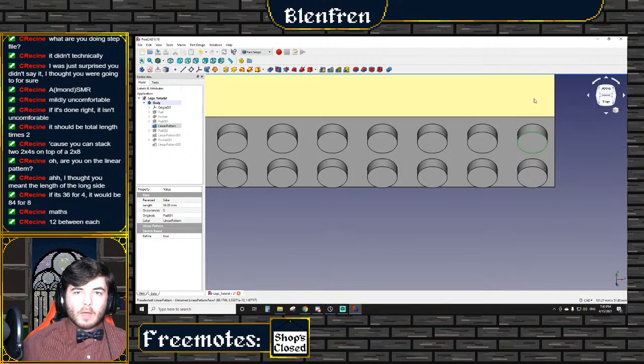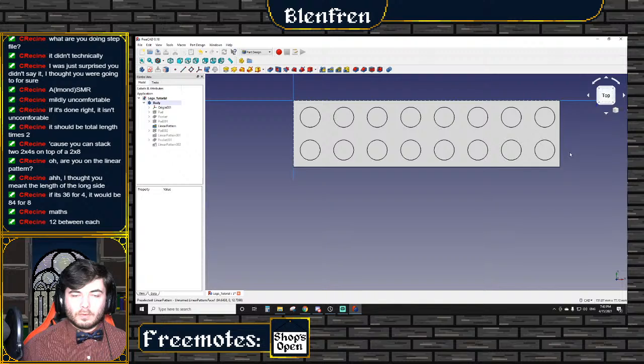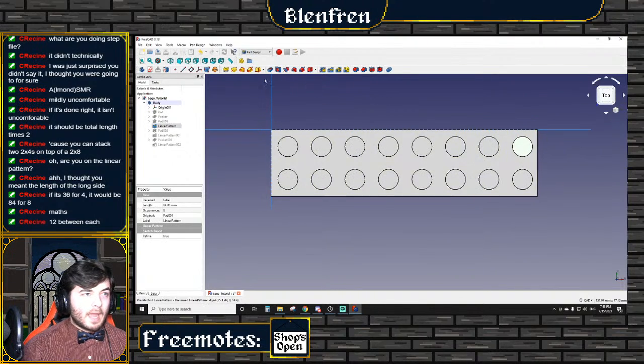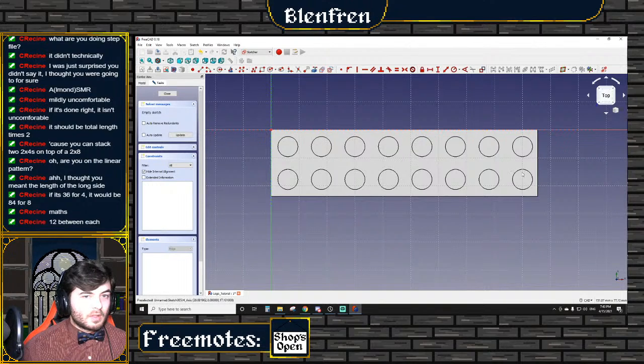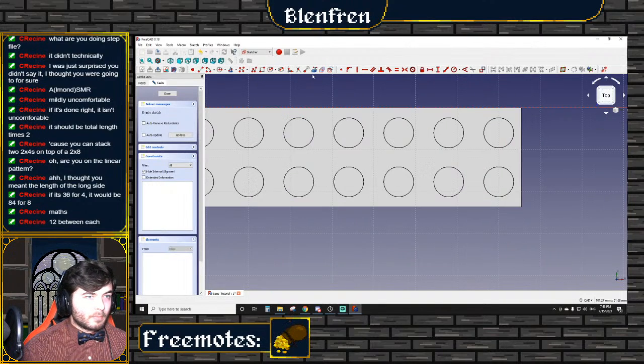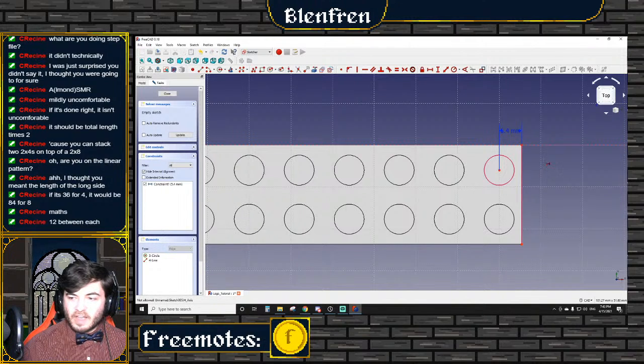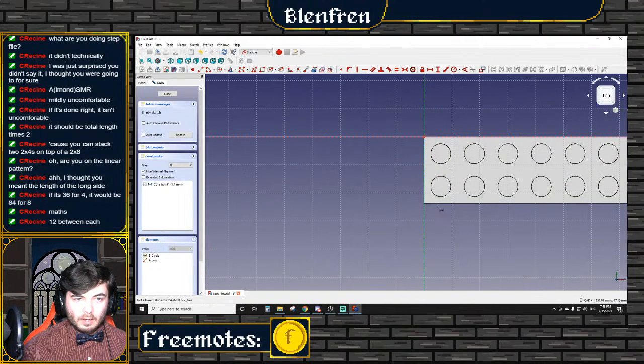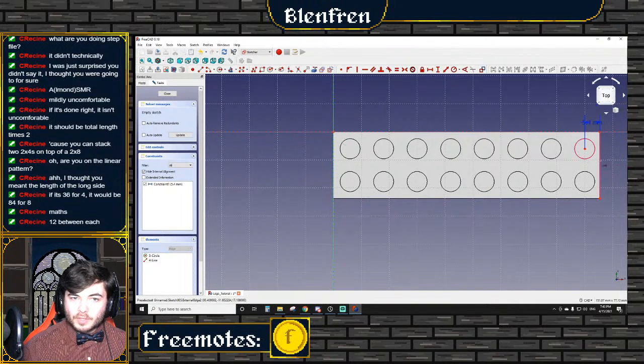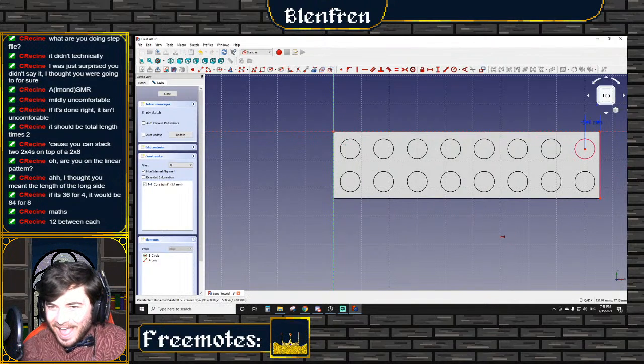Here's how we check. Go to the top view. Let's click on this face exactly. We can actually import geometry from both of these, this circle here, this line, and I can then click here and here. And it's 5.4 versus over here where it's 6. So it's not right.